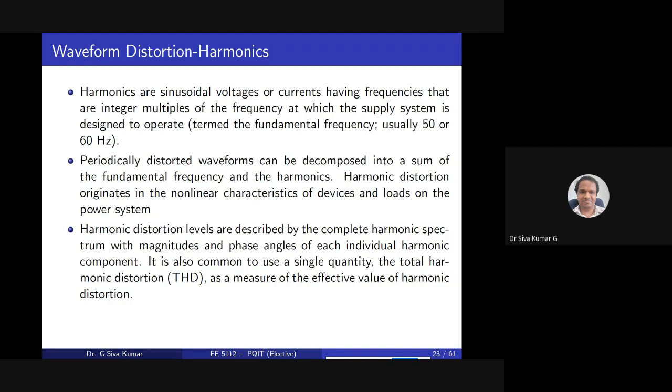Because of that we can eliminate, not eliminate, we can provide a path also. Whenever we talk about harmonics elimination, as I was mentioning in the earlier class also, we are not going to eliminate any harmonics. We are just providing a low impedance path for them, in order to not flow from the source.